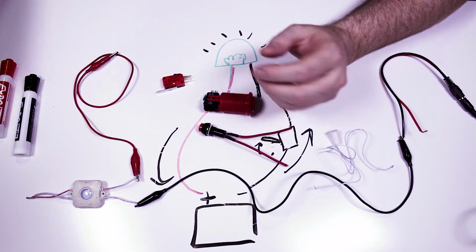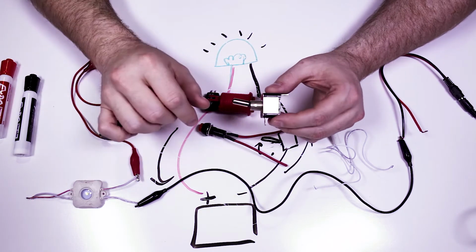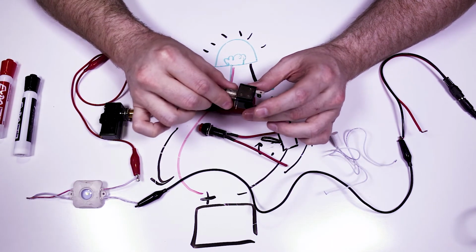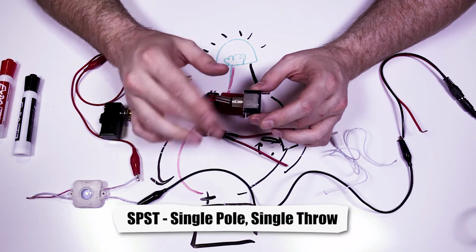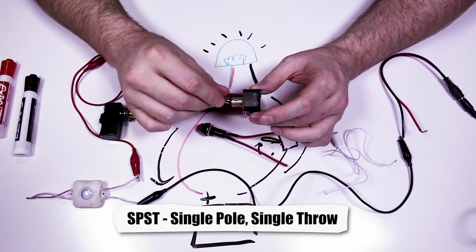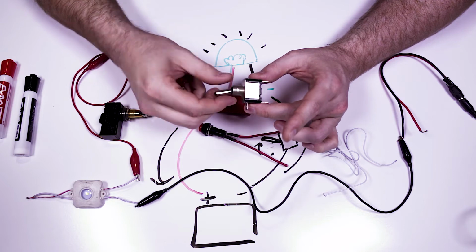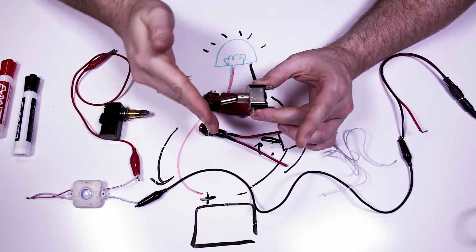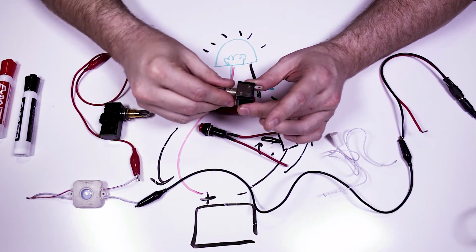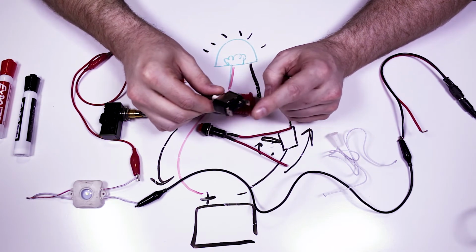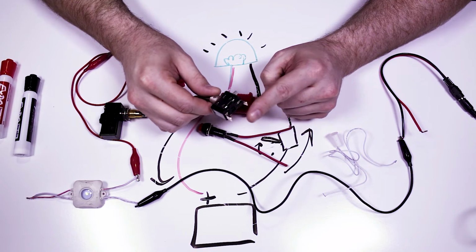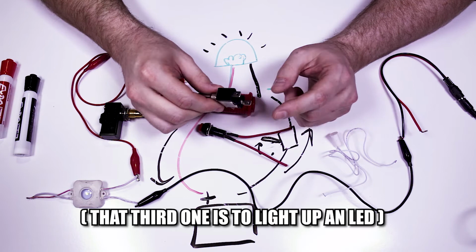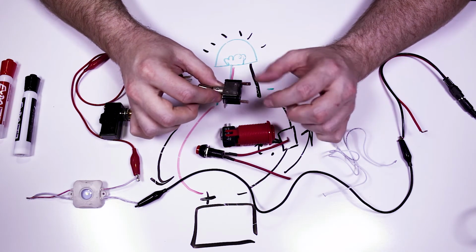And you've got your toggle switches, which are technically normally open and normally closed as well. This is what's referred to as a single throw, single pole. Single throw means it only goes in one direction. You have ones that have multiple positions. This is on or off. And then these are your poles here. So there's only 2 connectors. Some of them have 6, some of them have 3 or 4. It just depends. So again, something we can get into in a later video.